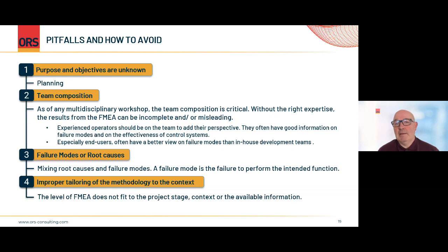Mixing up root causes and failure modes. The term failure modes in English, I think people intuitively interpret as something breaking, and so start listing off the components, or wear, corrosion, and getting a bit of a mix-up between the failure mode, which is the valve fails to close as it should, and the cause of that, which is wear or corrosion or fatigue or fracture of a specific component. But that's up to the chair and the team to try and keep themselves right on that.